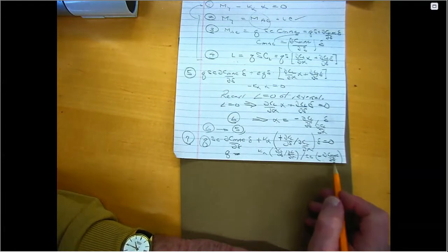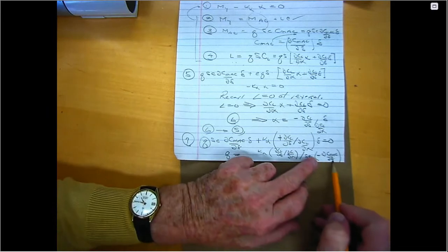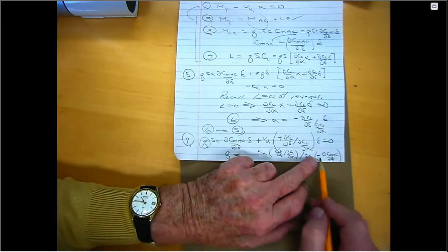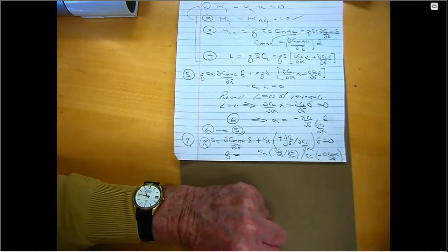And I put the minus sign there because my aerodynamicist friend told me, she swore this is true, that when she used an aerodynamic theory to calculate dC_MAC/d delta, or she took a rigid airfoil and put it in the wind tunnel and measured it, it turned out dC_MAC/d delta itself is not big enough. Because when I rotate this control surface down, I create a moment nose down, not nose up. So dC_MAC/d delta for a reasonable airfoil turns out to be a negative number, which means minus that is a positive. That's the key.